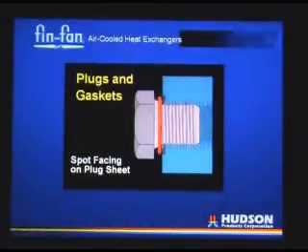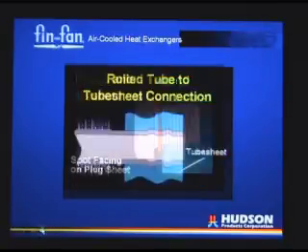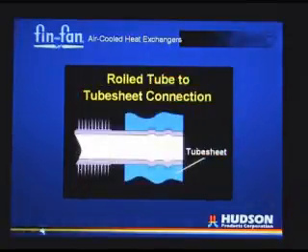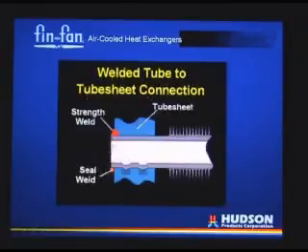To access a tube, in terms of fabrication, final tube rolling, everything is done through this plug hole here. This would be the plug sheet. On an adjacent sheet is the tube sheet, which we'll see in the next slide. The plug sheet would be over here. So you have to work through the plug sheet to roll the tubes, or to weld them in place with a seal weld or strength weld, like is shown here.